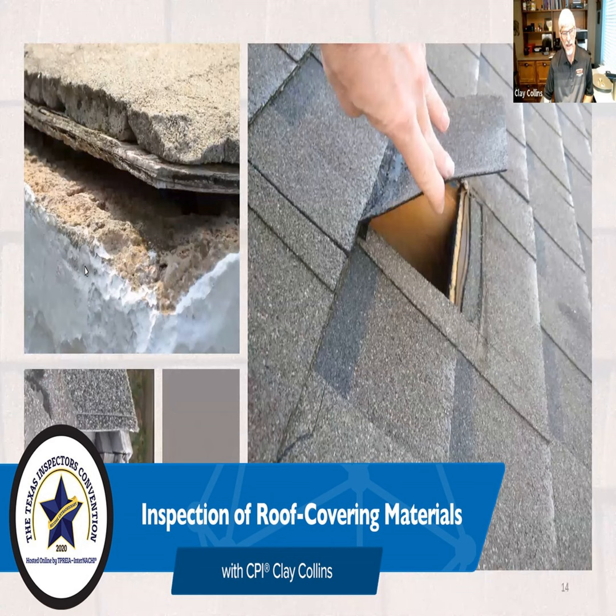I did not have access to the homeowner to ask about it, and the seller's disclosure did not note any problems because as far as they were concerned, it didn't leak. But we don't know which part of that roof is where the source of the water is. You can have an improperly installed valley, and we'll talk about valleys in a little while.